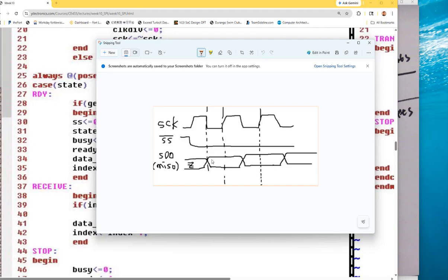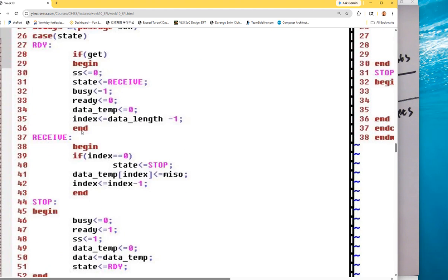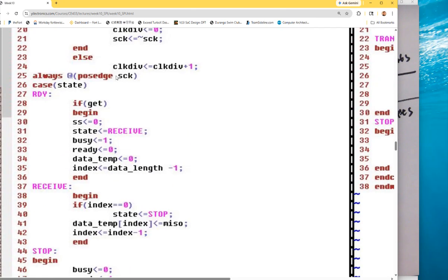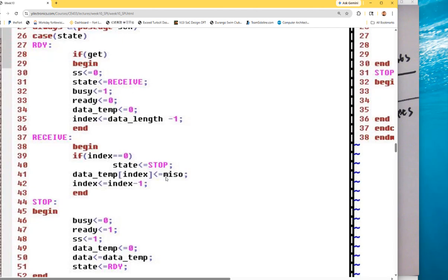So the falling edge will place the data over here. Data appears on the line, which is the SDO line, the serial data output. The SDO line will have the data from the ADC. Over here, there will be a 1 bit available. And the subsequent rising edge of the SCK comes from the leader. It's in this state, right? It goes to the next state already, because the first rising edge is already done. So this state will take the data in from MISO, or SDO.